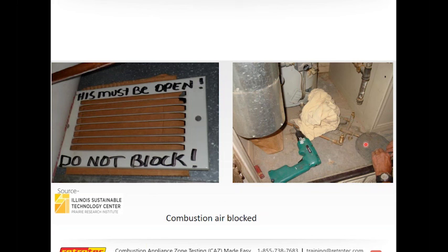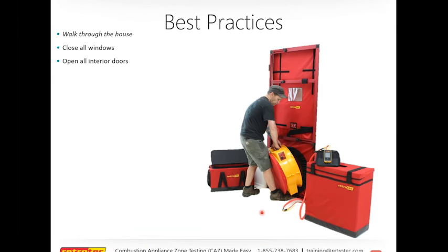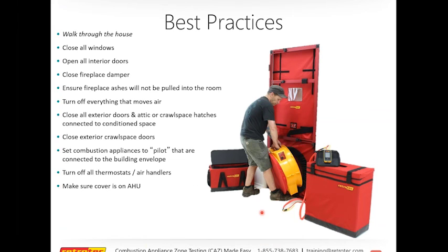And there's a picture from a weatherization where this is a relief pipe coming from the outside. Probably got cold in here, so somebody had stuffed a blanket in it and then closed it off. So they were not getting relief here, and you can see there's some elevated levels of deterioration and oxidation on some of these appliances, and it looks like the auditor dropped her lipstick as well.